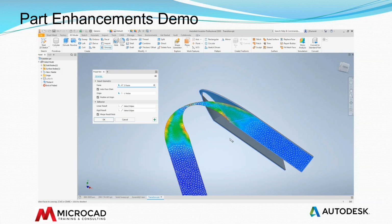Again, this is a one-to-one unwrap. No bend deductions, no K factors are being used here. It's a one-to-one unwrap. At least it gets you closer to where you need to be if it's going to be fabric or a really complicated form part versus just bent using the press brake. When I'm looking at this, once I select it and hit OK and accept it,